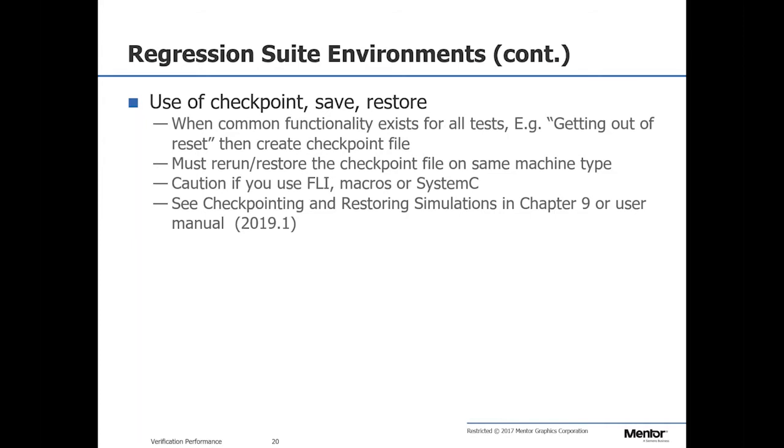The other use for checkpoint and restore takes a little bit of planning. Let's say you have a PCI link in your design, and you start your simulation. The first thing that happens is simulation elaborates, and then the PCI link goes into a training phase.